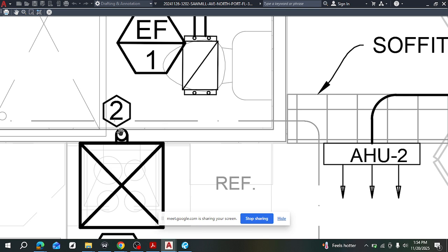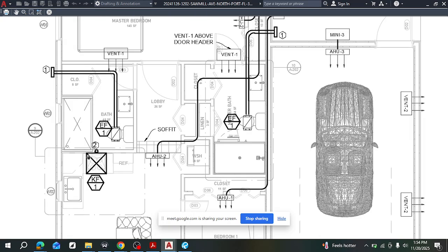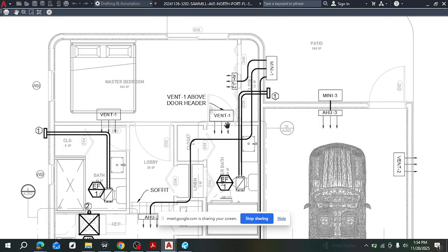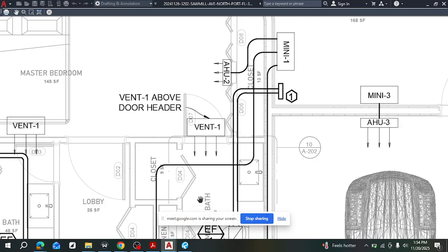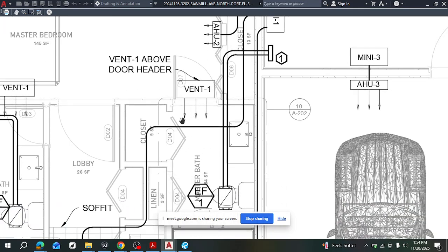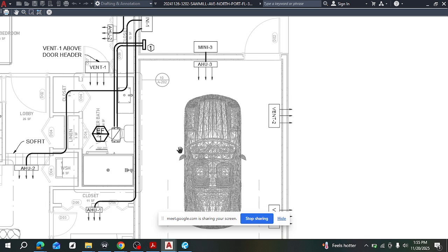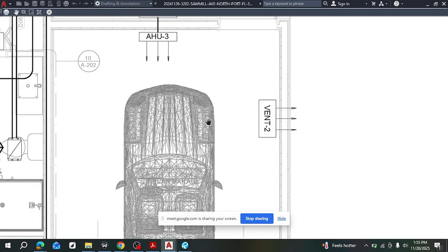In spaces like this, you also have to design with what they call negative pressure, to ensure that air always flows into the spaces, not out of them. Because if the air in these spaces escapes, it tends to contaminate the air of the other spaces. This vent fan, you cannot do it in reverse. If you notice, these arrows mean that air must go in this direction, not the other direction. So this bathroom is a space that air should not escape from but flow into. Another such space is also a garage.